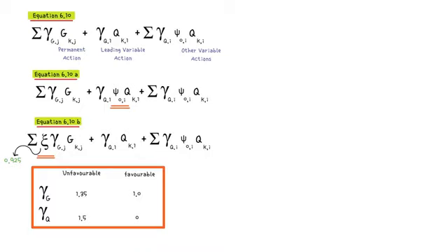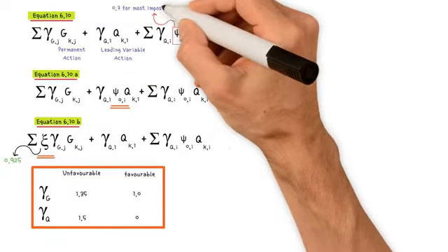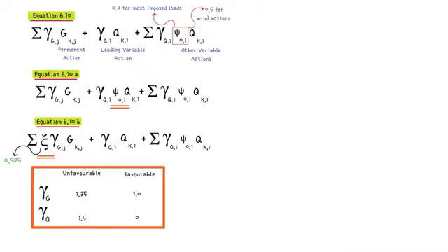In accordance with Table National Annex A1.1, values of psi factors for buildings, psi naught is 0.7 for most imposed loads and 0.5 for wind actions. First of all, we have option 1, we're going to be using equation 6.10. So, we have a partial safety factor for the permanent load, gamma g, and that's 1.35.